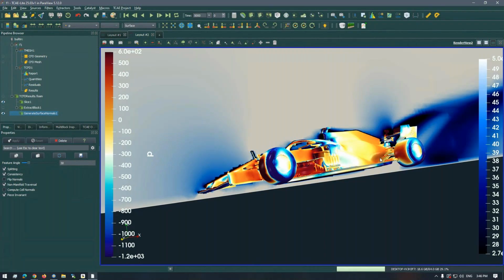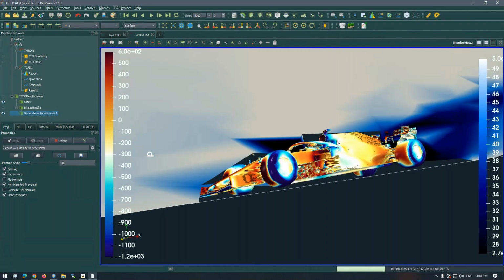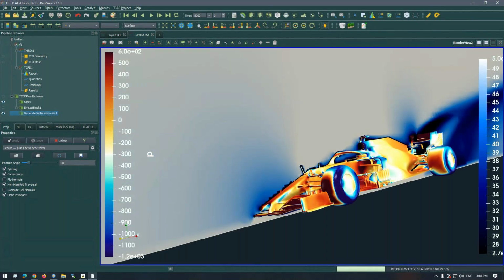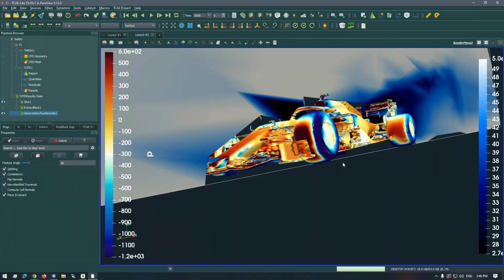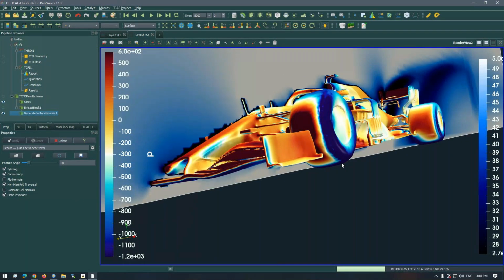But if you are certain about your boundary conditions and your physical model, and the simulation runs and converges, then ideally the residuals should fall down. And if everything is conserved, for example the mass flow rate across every interface, and the model losses are around the expectations, then you are on a really good way to have good results.